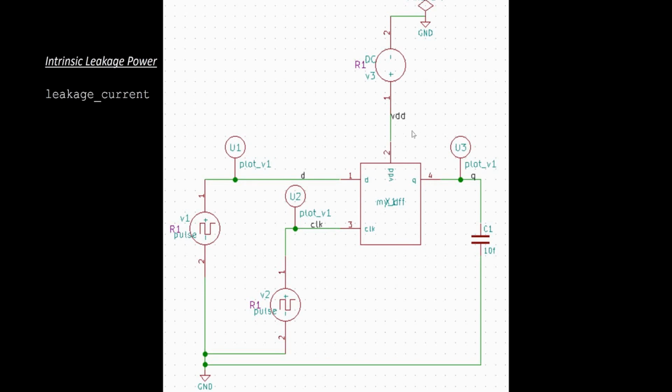There are two components of current over here. One component is the current entering into the cell, and another component is the current that exits out of the cell. These two components need to be modeled under the leakage_current group, and there is one more thing to take care of. The current entering the cell and the current going out of the cell should both be the same. Their polarities and directions will be different, but the value should be almost the same. If they are not, there is some additional component that needs to be modeled, and we'll talk about that when we reach there. To start with, let's look into the leakage current for this particular section.